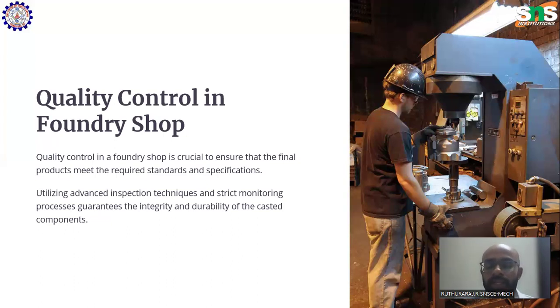Similarly, sand grains may get trapped inside the molten metal during the solidification process. They may lead to sand inclusion inside the casting. Those things have to be removed by cutting away the material. Those components will probably get rejected. To prevent that, you need to ensure that the sand is rammed properly. If the sand is rammed properly, there will not be any loose sand available. That has to be done to prevent the casting defects.